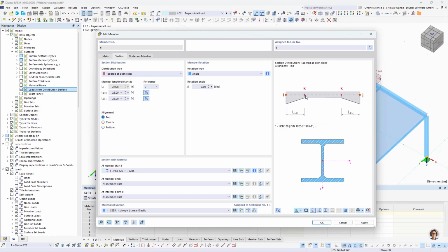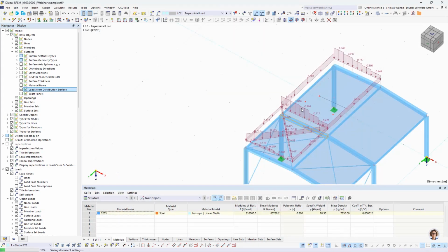If you enable the option, then for the tapered ends, the middle of the cross-section height would be applied. So in this case, the axis would have a little pitch. This can lead to small differences in the load transfer, but the difference should not be too big for most cases.